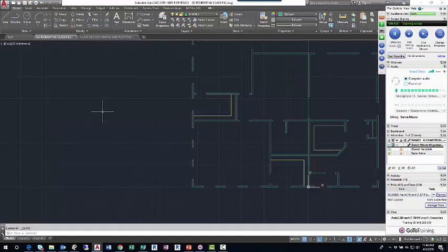But even still, even though we started this plan with the polyline command and direct distance entry and ortho, pointing in our desired direction, typing in our distance, we're still coming back to that offset and trim. With straight AutoCAD, if you need to put windows into window openings, doors into door openings, there's still going to be a certain amount of offset and trim to achieve that end.